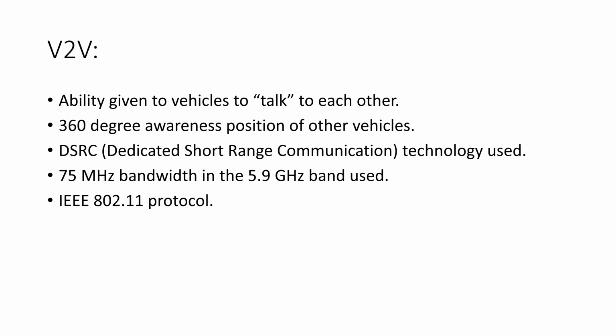Dedicated short-range communication technology is used to achieve this V2V connectivity that we are aiming at. A 75 megahertz bandwidth in the 5.9 gigahertz band will be used, and the IEEE 802.11 protocol will be used.